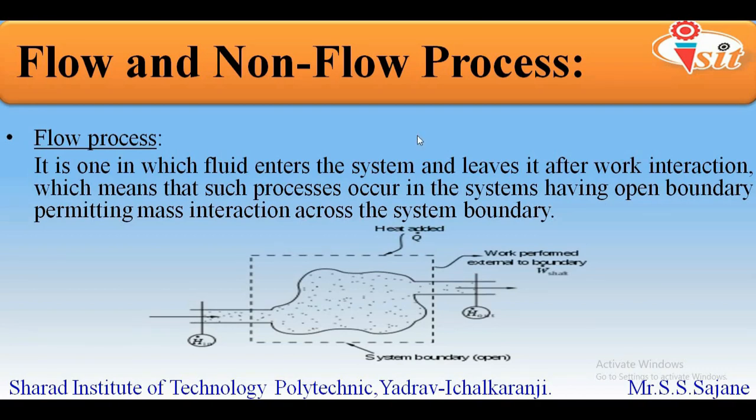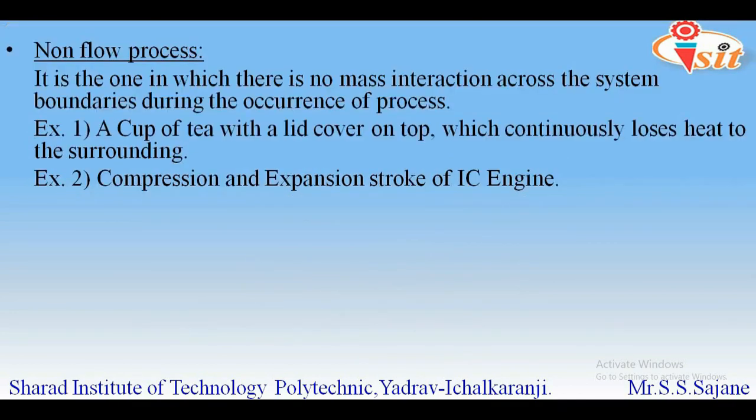In a boiler, what happens? Actually, water enters the system, and when we are giving heat to that system, this water is converted into steam, and this steam goes out of the system towards the turbine. So this is nothing but a flow process. We have seen the non-flow process.